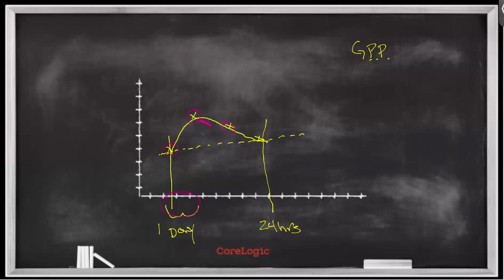Within that 1 hour window, if you notice a decrease in your humidity, you have humidity control. However, if in that 1 hour window, humidity is continuing to increase, you are not done with that initial visit. You should never leave a project where humidity is continuing to increase without an indicator that it's beginning to decrease, right? And that's really where we're going to spend the lion's share of our conversation today, around that particular problem. But you have to establish humidity control.